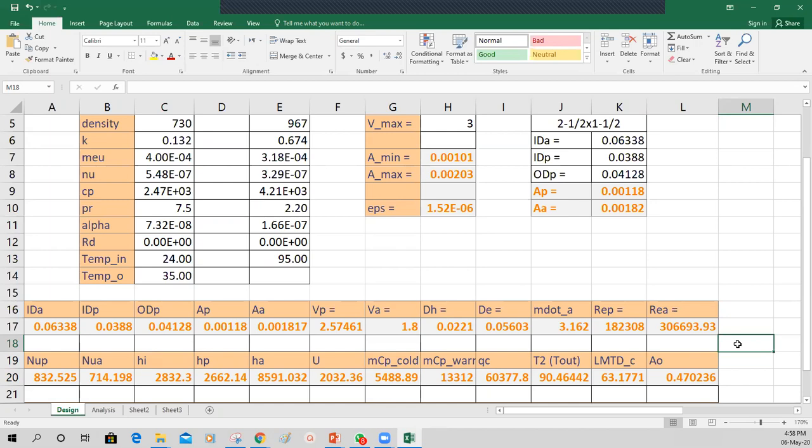So now we are calculating the heat transfer area, so that will be the outer area. We calculated hi, then converted to ho, and this is on the outer surface of the tube. Exactly. So now we can calculate the length. How much is the length now? 3.62 meters.